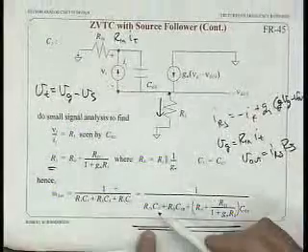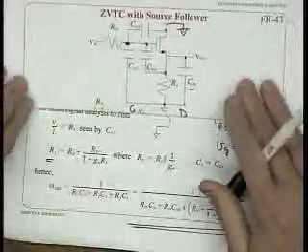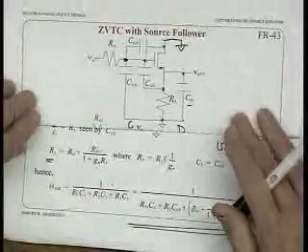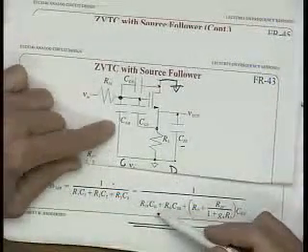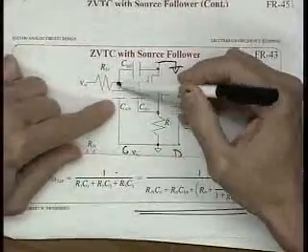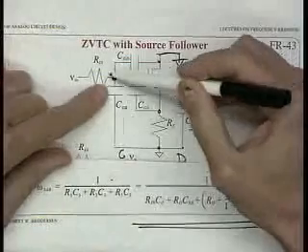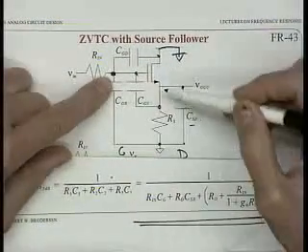So what do we end up with here? Let's go back to our original circuit. So here's the answer. 1 over Rn times Cg. So here's Rn times Cg, and that was Cgb plus Cgd. So that's kind of the input capacitance seen here. There's an R out.